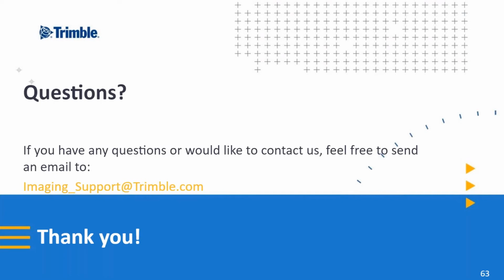Certain datum for base station. In the profile manager, in the coordinate manager of your base, as explained by Carl, you could set your base coordinates properly, and you could use the reference frame of your base.